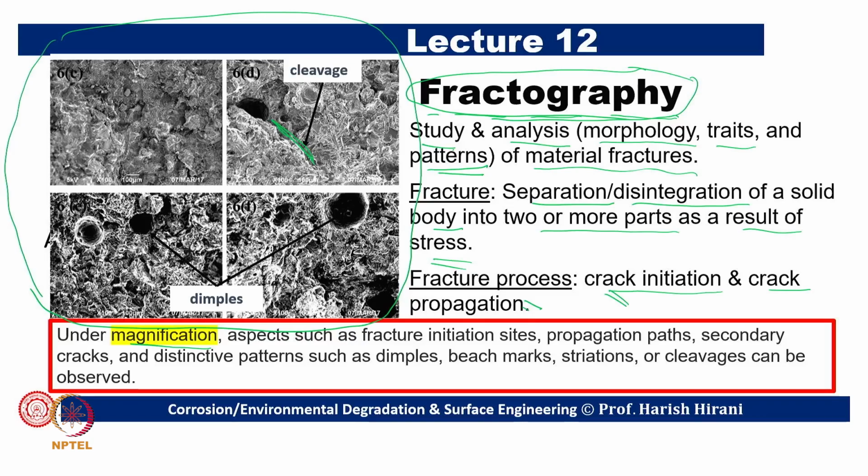Under magnification we want to look at the fracture initiation sites, the propagation paths, the secondary cracks leading to further failure, and the different patterns. In this case we have shown the dimples, and we also discussed in earlier lectures beach marks, striations, cleavage and many more such patterns.